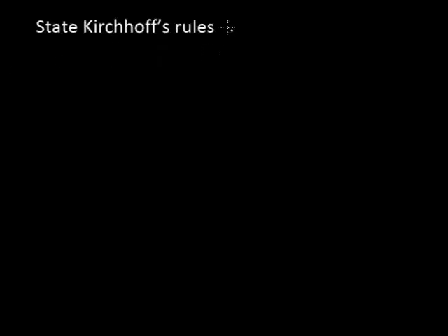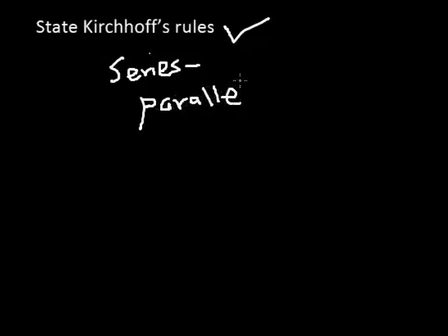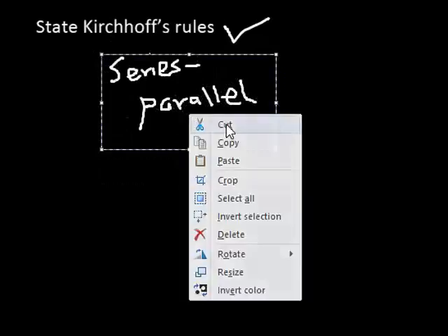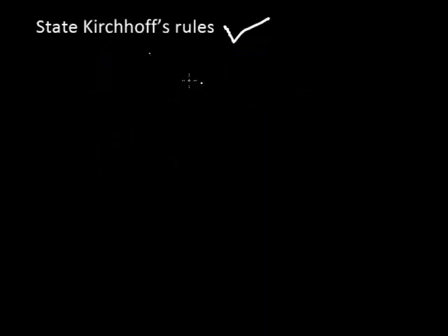But before then, let's look at Kirchhoff rules. Why do we apply Kirchhoff rules? There are some circuits, some networks, that you can reduce to series and parallel like we did before, where we differentiate a series and a parallel connection of resistors. Now there are some circuits you cannot reduce to a series-parallel connection. In such a case, you apply Kirchhoff rules.